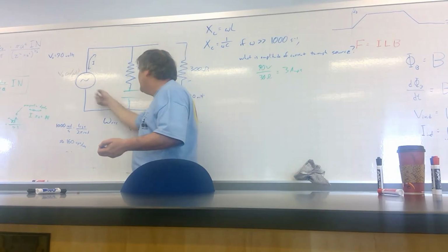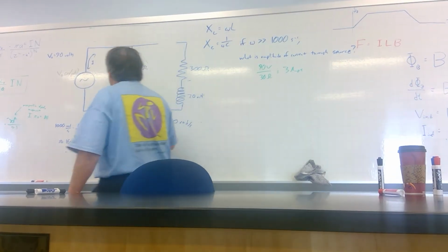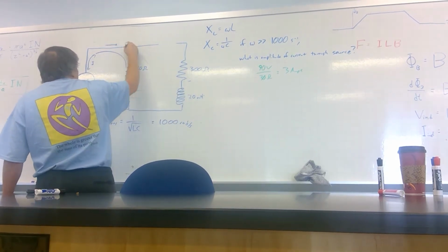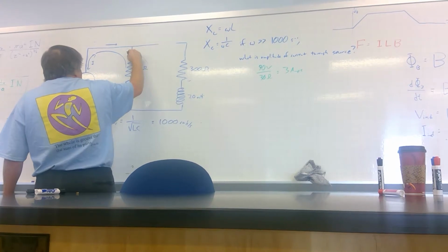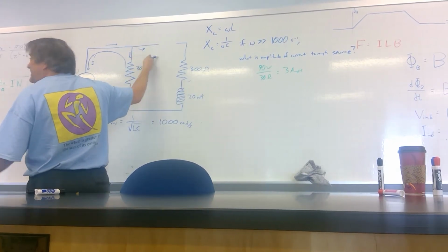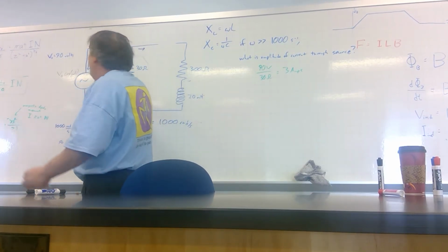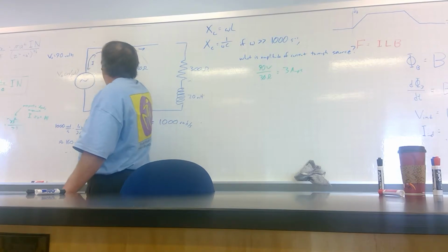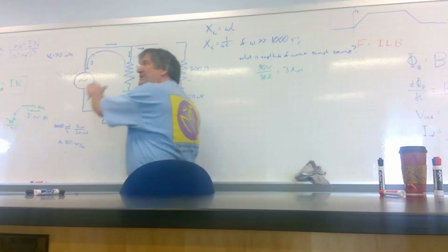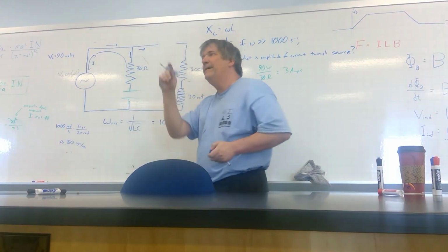And the source is feeding current just through this branch. You could say, hey, there's Kirchhoff's rule again: the current coming out of the source is going to do 2 things. It'll feed current down this branch, and it'll feed current down this branch. But if this branch is essentially incapable of accepting any appreciable amount of current, then the current from the source is just the current through this branch, and that current is really just following Ohm's law. The capacitor is acting like a 0 impedance thing.